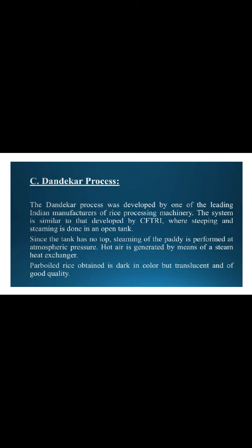Then the Dandekar process is developed by one of the leading Indian manufacturers of rice processing machinery. The system is similar to that developed by CFTRI, where steeping and steaming is done in an open tank. Since the tank has no top, steaming of the paddy is performed at atmospheric pressure. Hot air is generated by means of steam heat exchangers. The parboiled rice obtained is dark in color but translucent and of good quality. This is the Dandekar process parboiling plant.